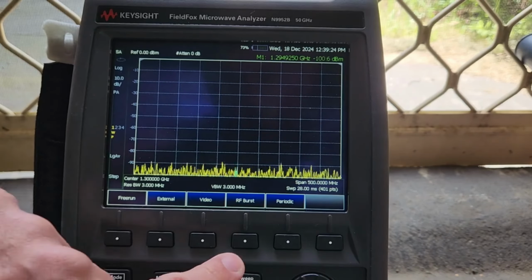You can see that all these activities happen when the signal is up and quite close to the trigger level, and all this is caused by the turning on of that leaf blower. We can always change back to the 0 span to see what's going on, and then change its resolution bandwidth to the highest because we want to see what the pulse looks like.